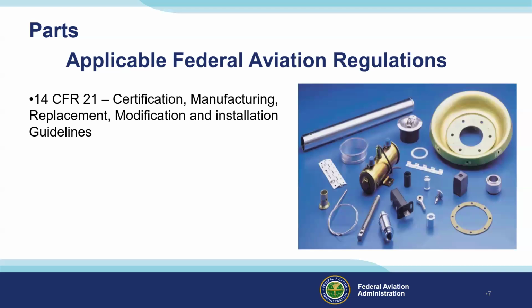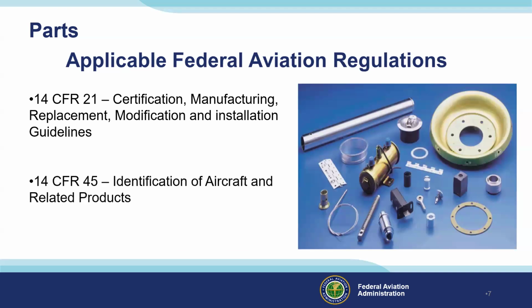The main regulations pertaining to parts are Part 21, which covers certification, manufacturing, replacement, modification, and installation, and Part 45, which is identification of aircraft products and related products.